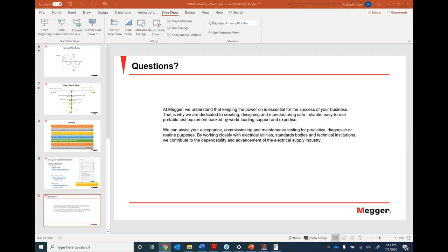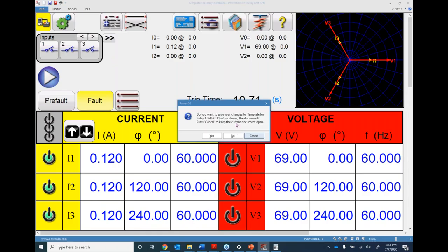So you can save a configuration file of 115 volts and 1 amp, and you can also do it at 69.28 volts at half an amp, and you can set those up as PDB XML files and just load them each time that you want to perform a test. And eventually, when you get to the end of the configuration, you're actually doing your same test over and over. Your configurations follow you each time.